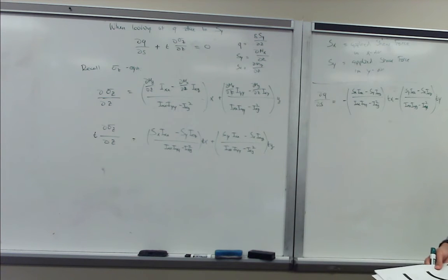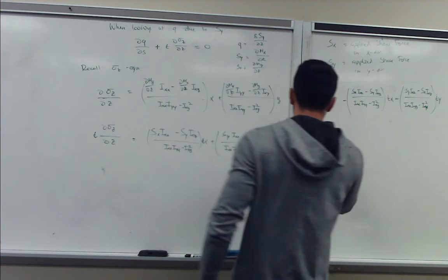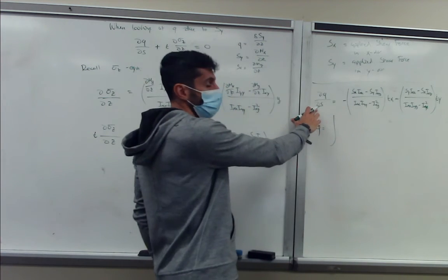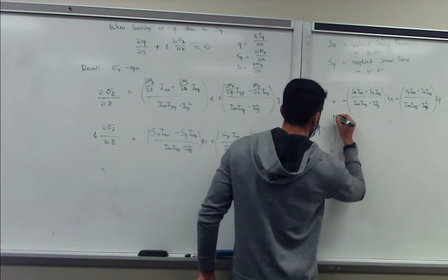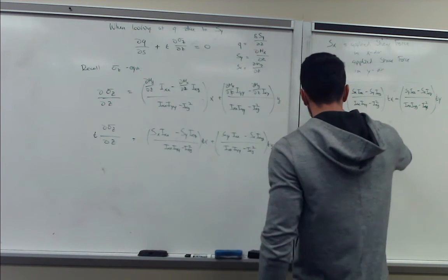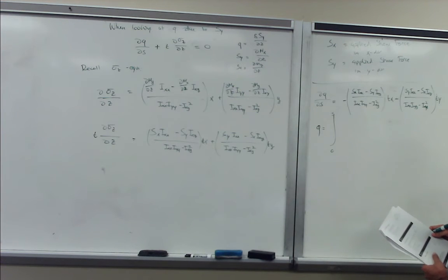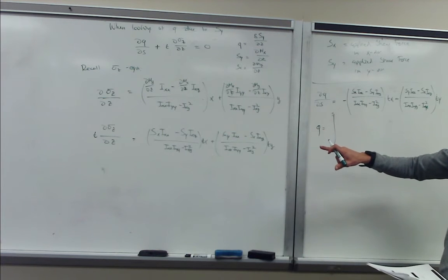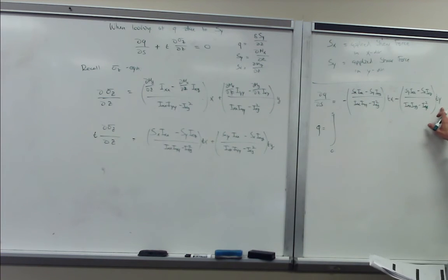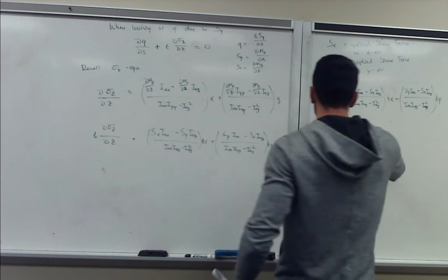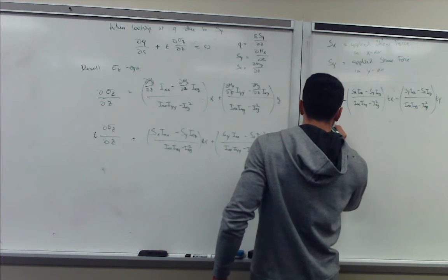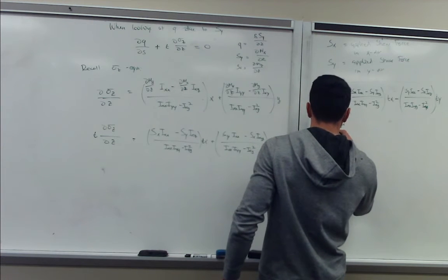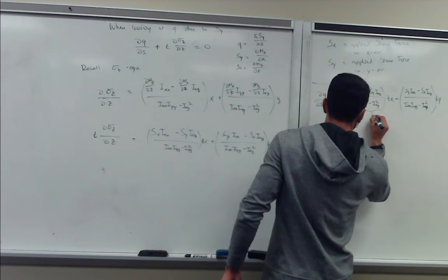So if you want the shear flow, we can just take the integral. In this case, q is equal to the integral, and since we're taking variation with s, our integral goes from 0 to s. Then we have to identify a couple more things. The applied shear force does not vary with s. Only tx and ty do, or the coordinates x and y. So we can rewrite this with Ixx Iyy minus Ixy squared as just delta.